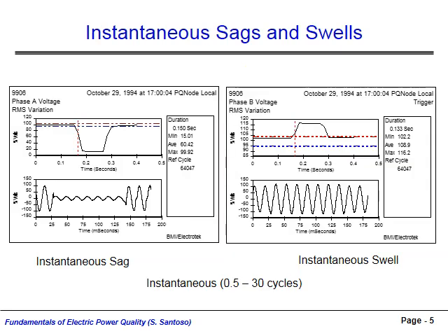A voltage swell occurs when the RMS voltage magnitude increases to above 110% of its nominal value. The 2 figures compare the RMS and instantaneous voltages of phases A and B on a power system during a short-circuit fault event on phase A. Note from the timestamps that the 2 figures show the effects on 2 phases of the same fault event. Phase A experiences a voltage sag, dropping to 0.15 per unit for about 0.15 seconds. While it does not experience the fault directly, Phase B experiences a voltage swell, increasing to 1.16 per unit while the fault is on the system.